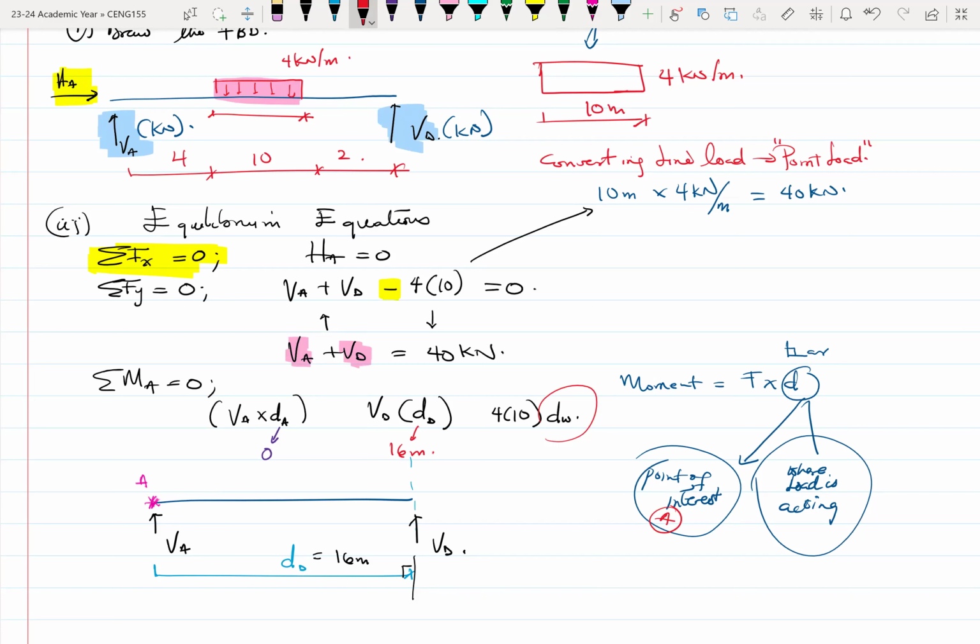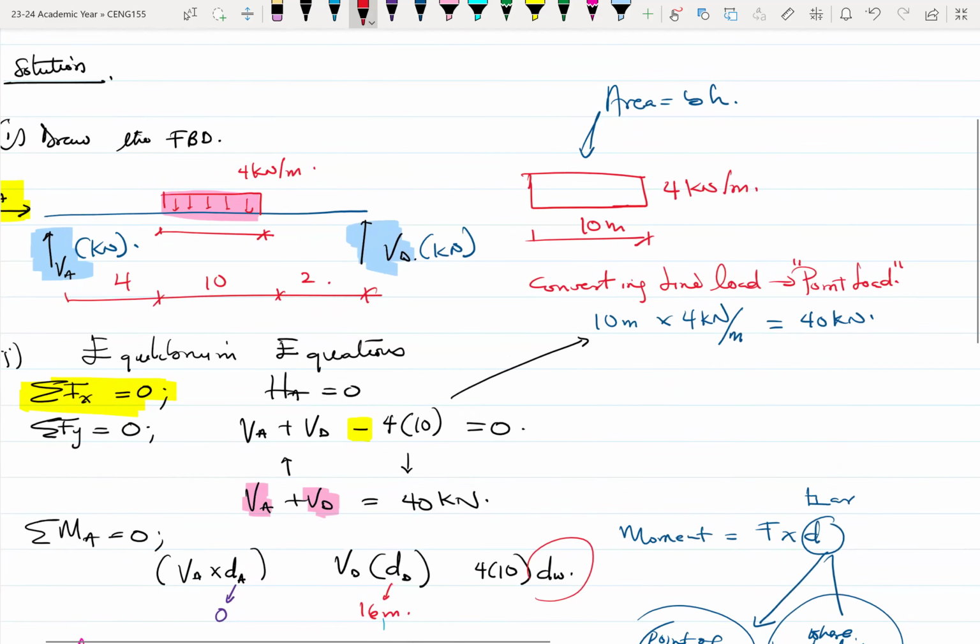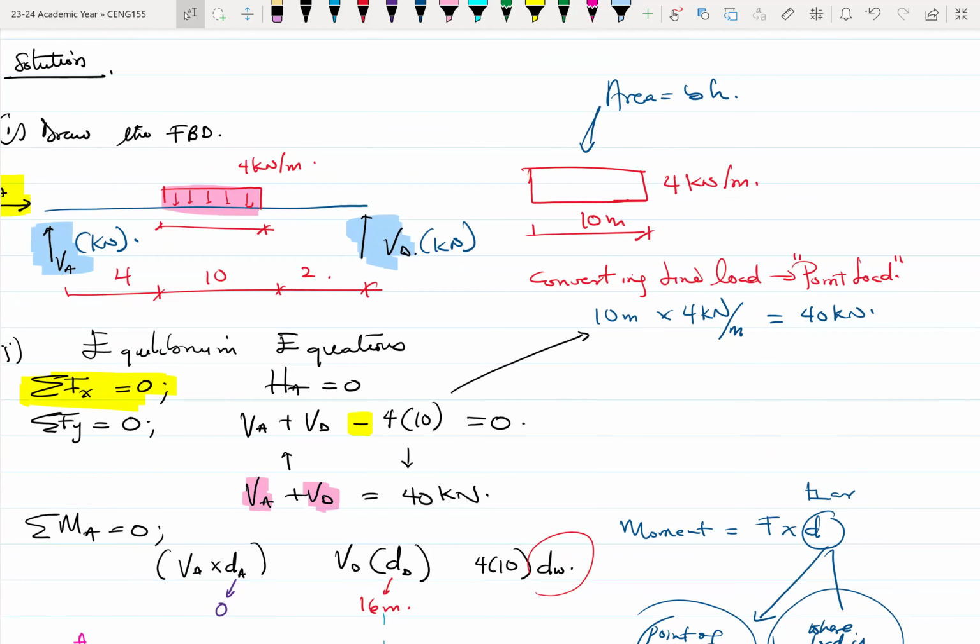In your physics class, I think as part of one of your practicals, you were balancing a ruler or a bar over a knife edge. Pretty much what you were trying to do was to find the center of gravity. So if that ruler is perfectly made, its center of gravity will be at the middle portion of the ruler. So if you come back and look at a rectangle, its center of gravity is at the midspan.